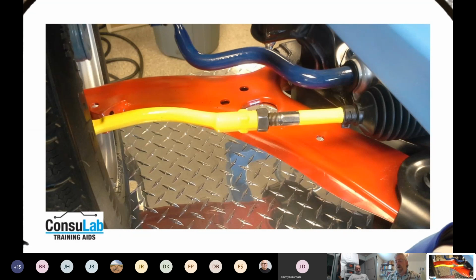The arc clears the wheel and tire on this because of the offset of the wheel, which again was calculated when they did the scrub radius of this. So they determined where the wheel had to be mounted, and then we have to accommodate for this. So you can even get into problems if you put one of these on the wrong side of the vehicle, where you could actually have the wheel contact the arc of this. So just some interesting things that you could run into.